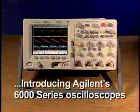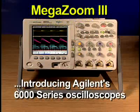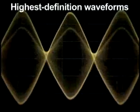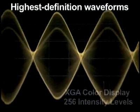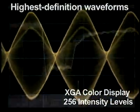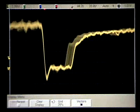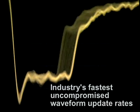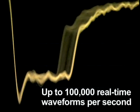The good news is, Agilent's new 6000 series oscilloscopes with MegaZoom 3 technology are the very first digitizing scopes to exceed the display quality of traditional analog scopes by providing z-axis display intensity gradation, the third dimension. In addition, this new series of scopes provides the fastest uncompromised waveform update rates in the industry, the fourth dimension, up to 100,000 real-time waveforms per second.